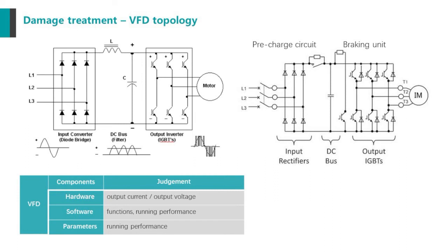By the way, some customers use a pump for maybe more than 5 or 6 years, and then they start using the VFD, and suddenly the motor could easily be damaged. This is also due to the difference between the PWM waveform and a pure sine wave.